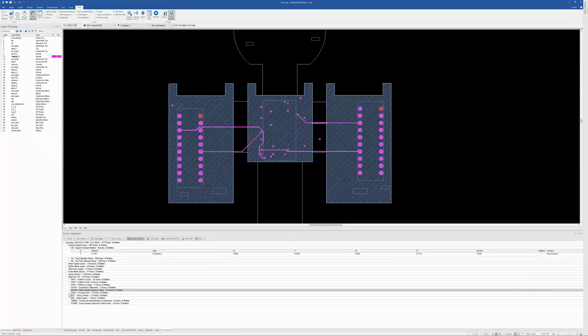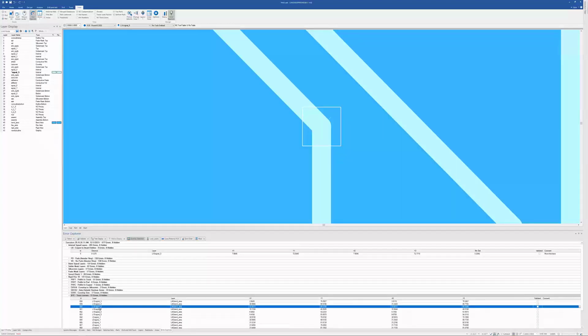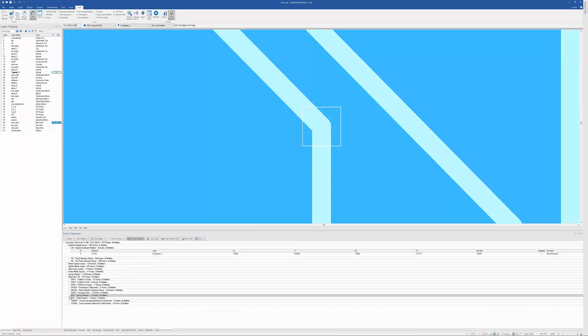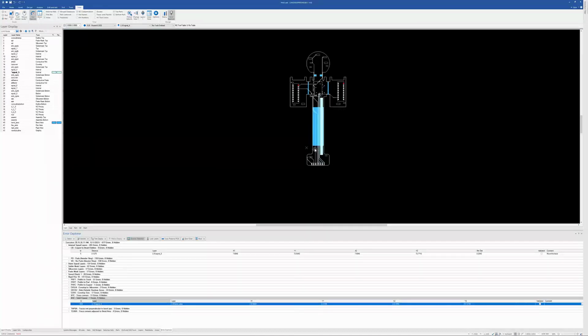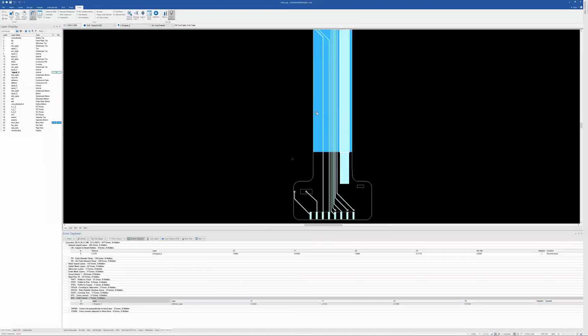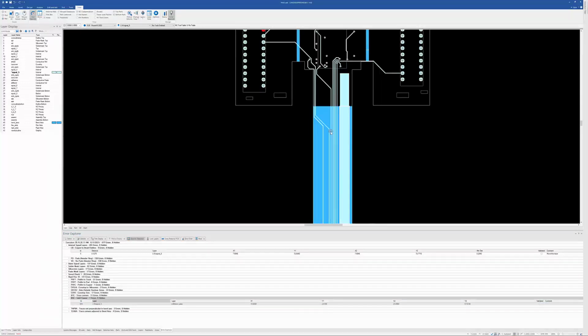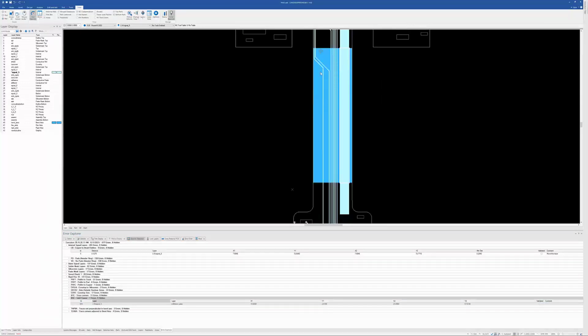And then cover lay size, trace corners is a good one. You do not want those in a bend area. So these are bend to trace corner. And here's our solid copper check. Solid copper is this color blue here. And it's basically telling us that, hey, you got solid copper in a bend area. That is not something you want.